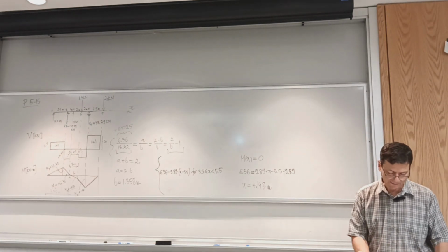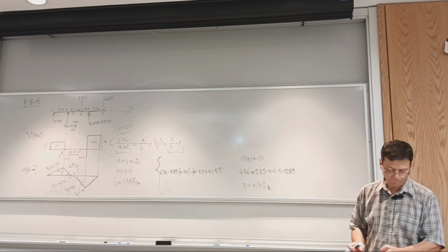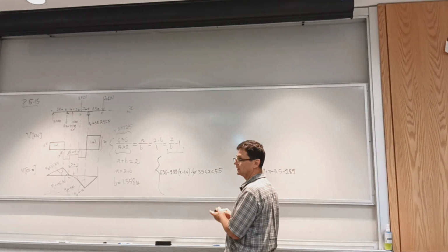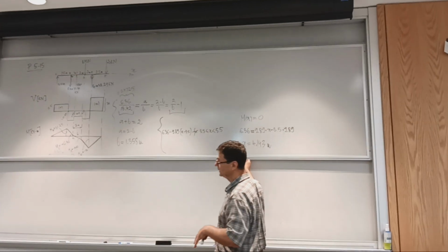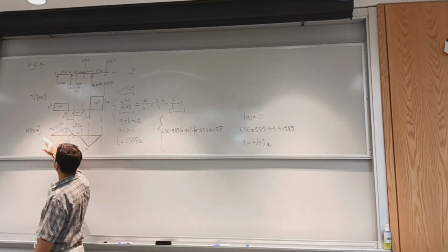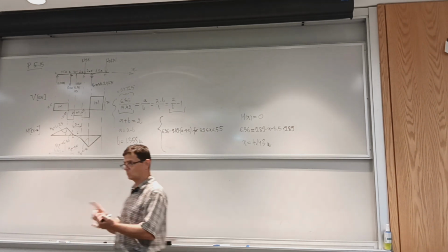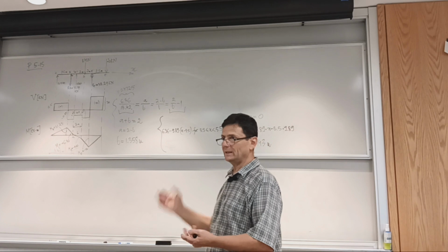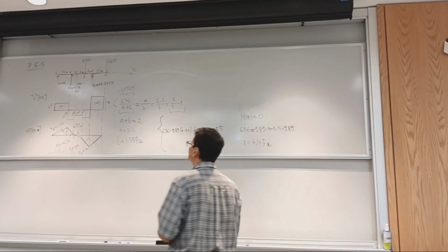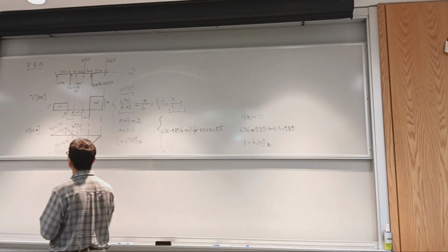Nice problems, but again, they're only like half of what is usually done for this kind of analysis. Once you have the moment diagram, you can evaluate stresses. You need to know the equation of the moment, and then you need to know area properties, to calculate the stress at that location.